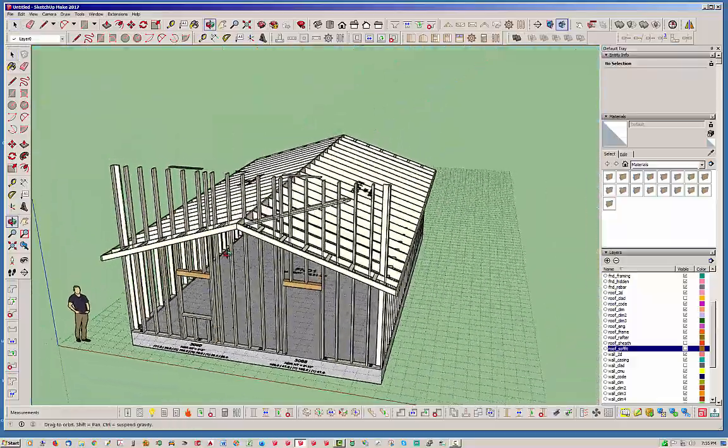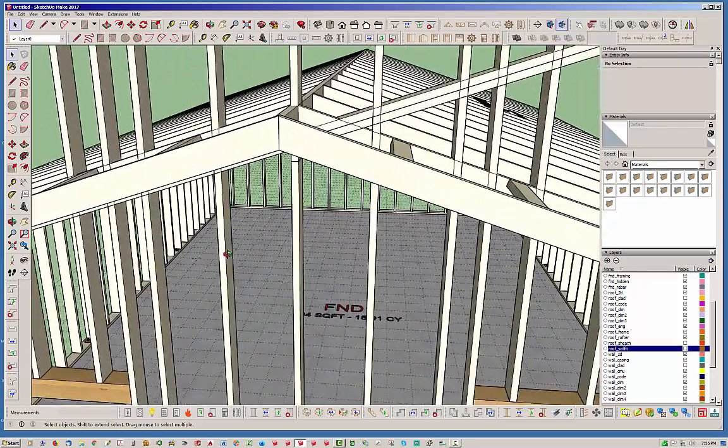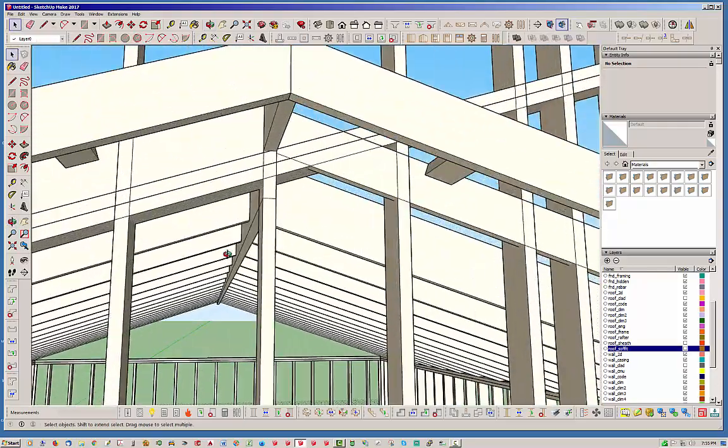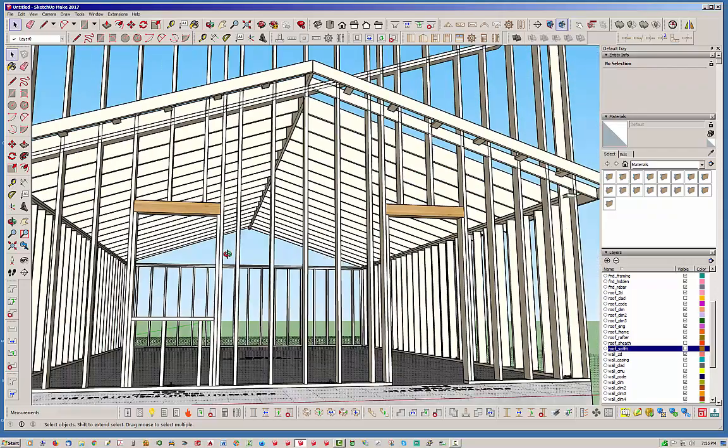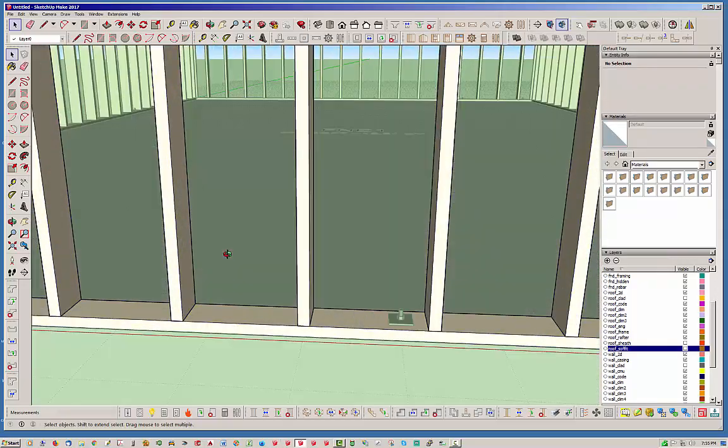So now we just shove those all down there, and then the next thing I'm actually going to do is, you'll notice how this stud just happens to line up centered on that. Well, I actually want to do a double stud there. It's not a requirement per se, but that's just the way I'm going to frame it up.